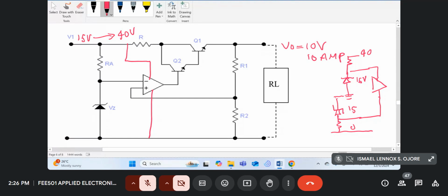So if you use a transistor whose VCE max is 30 volts, then if your regulator gives a lower voltage, for example, in the case the load is short-circuited so that the output voltage is almost zero, it means the full voltage of about 40 volts is applied across the transistor Q1, and the full voltage minus VBE of Q1 is applied across the collector and emitter of Q2.